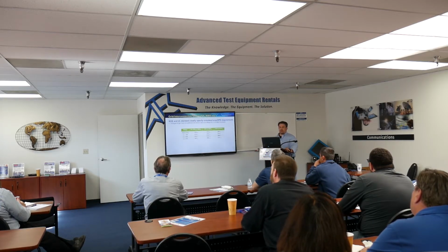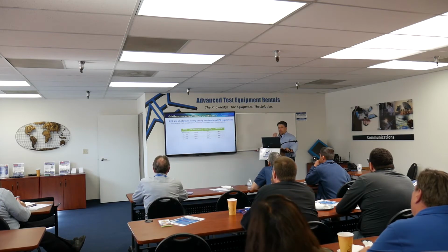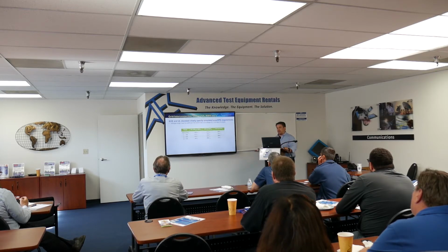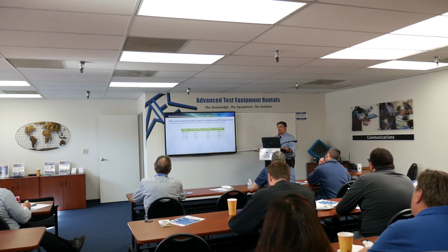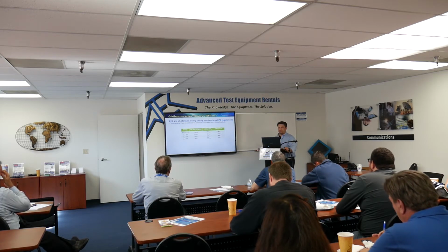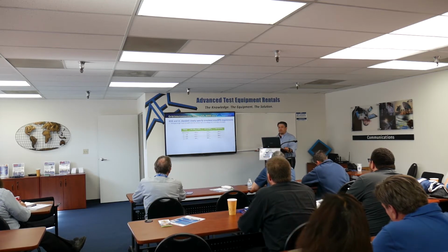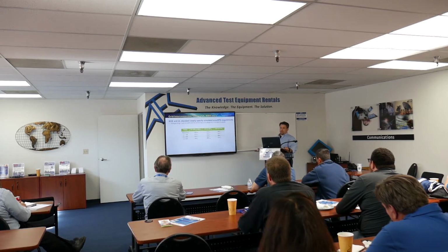Then the other thing I want to talk about is the AC side, which gets into our grid simulator. We talked about the DC side going both directions, emulating a battery. But with AC, this comes into play as well, especially with a lot of the EV stuff in the market now. Some manufacturers are starting to do vehicle to grid, where vehicles push power back onto the grid. There are also standards like IEEE 1547 and UL 1741, where you have to test to a certain percentage over the nominal voltage.